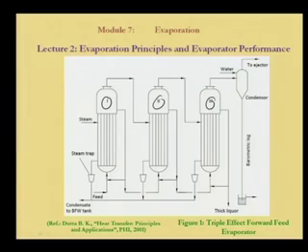But the point over here is that when we put the feed in, the pressure is high, so the boiling point is high, but the liquid is a dilute liquid. As it boils, it gets concentrated and goes to the other ones. Once it is concentrated, its boiling point increases, as we have seen in boiling point elevation. And what we want is for its pressure to be reduced, so it works in the favoring direction.